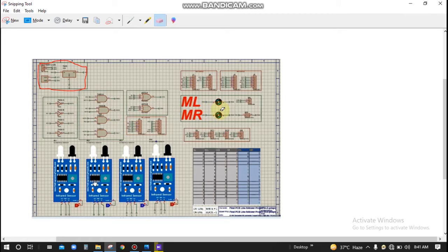Okay, so these are the two motors, and these are the four sensors. These sensors are basically sensor left, sensor right, sensor center 1, and sensor center 2. These will detect the black and white surfaces, and these are the two motors, motor left and motor right, and these will ensure the movement of that robot. These are basically the silk connections that we will use to give extra connections for the ICs, so that if any terminal burns, it should be available for us.